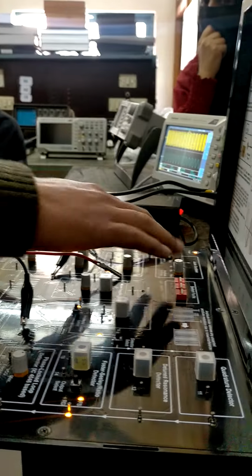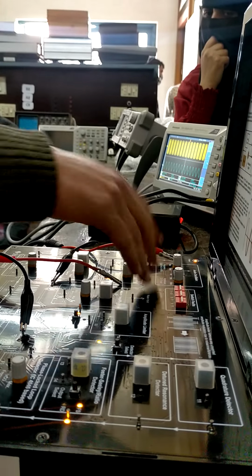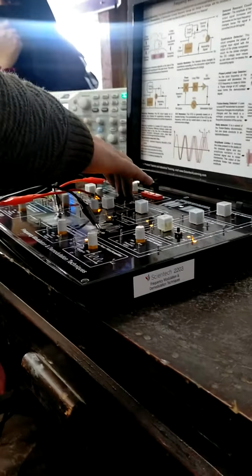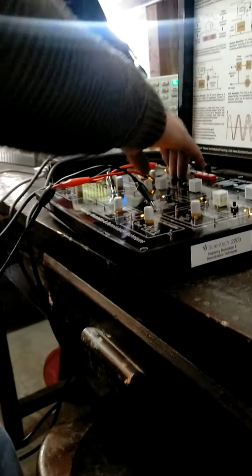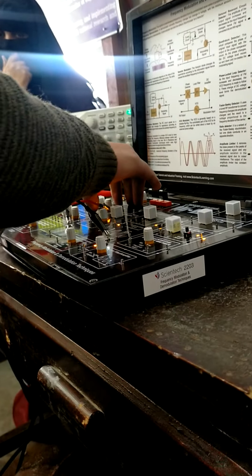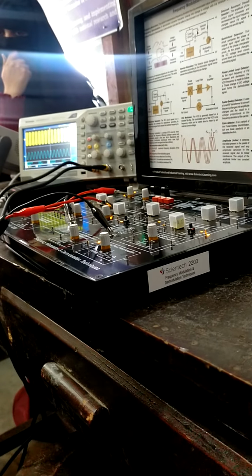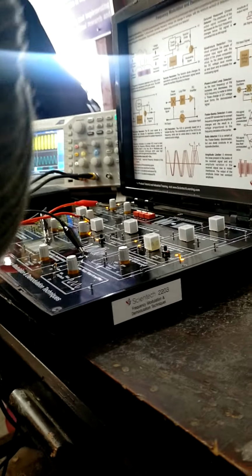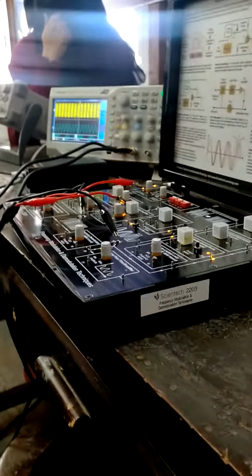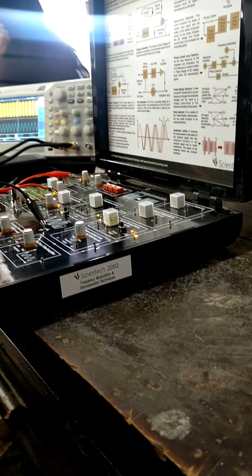Now in this case also we use a particular audio oscillator in order to generate first of all the message signal. Okay. And then that audio oscillator's output is given to a reactance modulator or any other modulator which is an FM modulator. There are various types of FM modulator. Vector modulator is one, reactance modulator is another, and there are various ICs which also do the FM modulation process. Okay. So you can use any of those modulators in order to generate the FM signal.